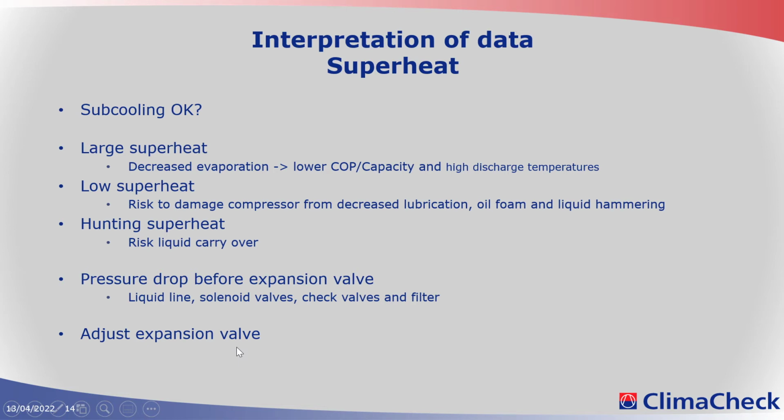So don't adjust your expansion valve before you have seen that it has proper operating conditions. If you change the expansion valve on a system that has low charge, creating some flash gas to the expansion valve, you are at risk that when somebody later comes and recharges the system to correct charge, your valve is too open.